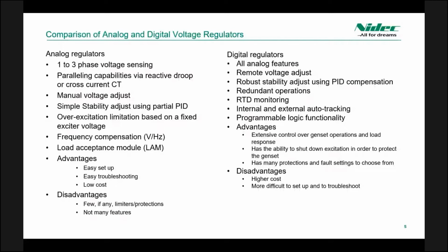Digital AVRs can be connected for redundant operations, so in the event that one AVR fails, the other can take over in its spot. RTD monitoring, auto tracking, and programmable logic functions are common features offered on digital AVRs. The biggest advantages digital regulators provide are the integration with programmable logic controllers, often used in control panels, and they have many programmable protections. Cost and complexity are notable disadvantages.